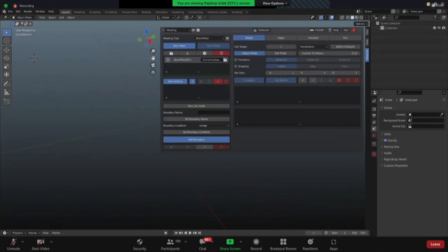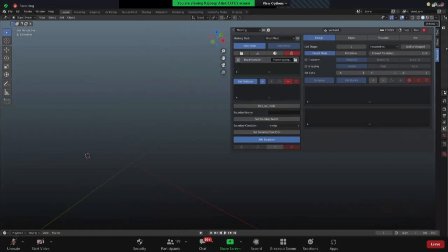Yeah, so in this view section, you have this option called this hand. Can you see this option? If you hold this, you can pan the view and you can move it around as much as you want. With the middle mouse button, which is the scroll button, if I put my cursor into the view and I hold it and move my mouse around, I can rotate or orbit this around. So in that way, I can work around with my 3D view.